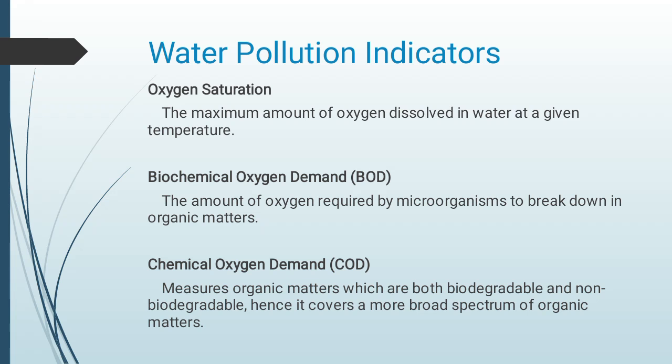Biochemical oxygen demand, also called BOD, the amount of oxygen required by microorganisms to break down organic matter. Chemical oxygen demand, also called COD, measures organic matter which is both biodegradable and non-biodegradable. Hence, it covers a broader spectrum of organic matter.